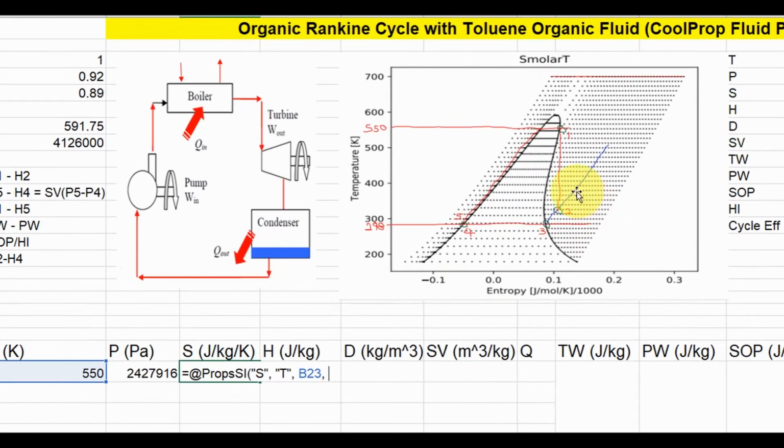But before we enter the pressure, we know that at this point, the fluid is in its gas phase. So we need to specify that in the CoolProp string. So all I will do here now is put in my inverted comma, and I put P, and I specify the string that at that phase the fluid will be gas.